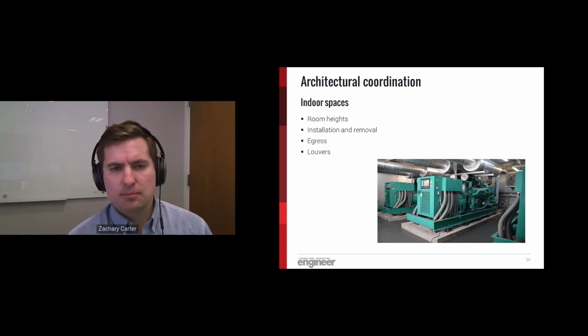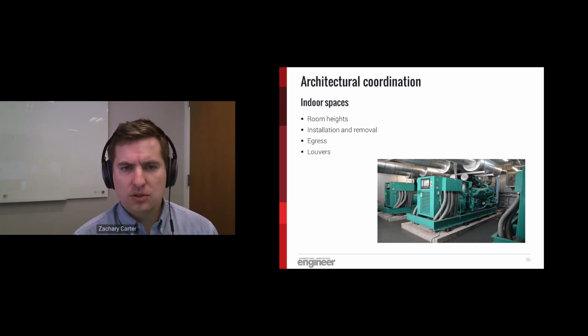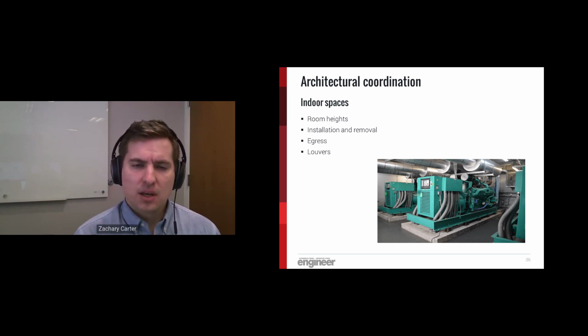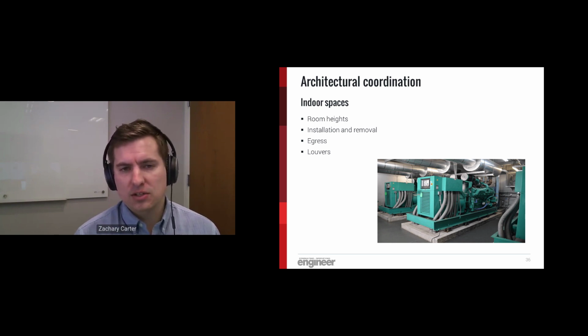For indoor spaces, room heights are a concern. We also need to consider, it might be easy to install it day one. Contractors have the right tools and equipment and space it correctly, but we also need to be thinking of how we're going to remove or replace that in the future. Also, how are we getting around the space, and louvers for intake and exhaust coordination are important as well for indoor generators.